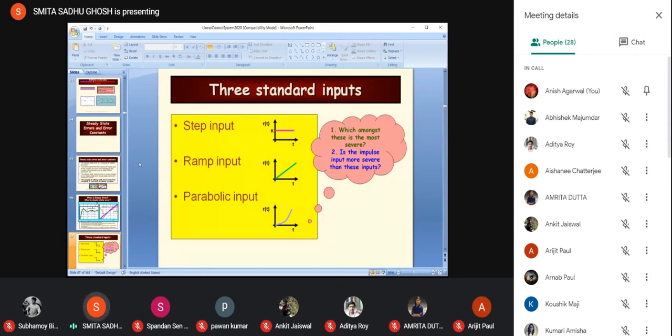In most cases, meaning for specific cases, we will come to many such cases as we go by, where, say for example, the ramp response is what you have to see, otherwise it's going to become trivial. In those specific cases, it's a bit different. But apart from that, the step input is the one which is normally preferred as a signal to be applied for the analysis of systems.